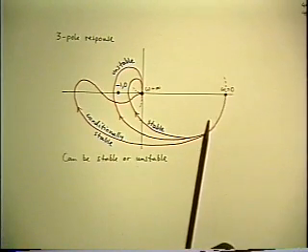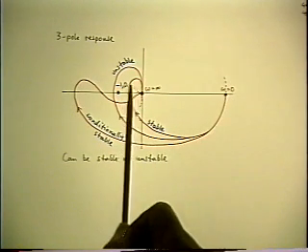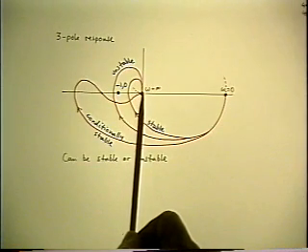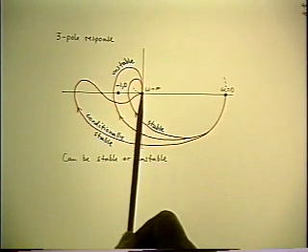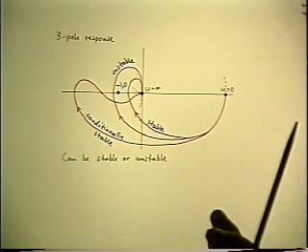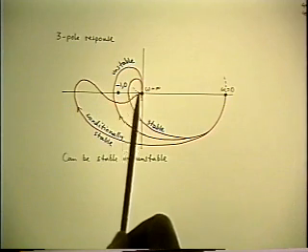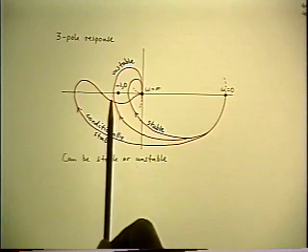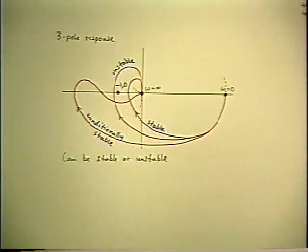Take the smallest of these contours. This is three poles now because you end up at infinite frequency with zero magnitude, but from the 270 degree direction, 90 degrees from each of the three poles. And the answer now to the stability question is, well, it could be stable or not depending on the size of the contour. The smallest one is stable because it doesn't go around -1, but the next one out, which is basically the same shape, is unstable because it's bigger and it does go around the -1 point.